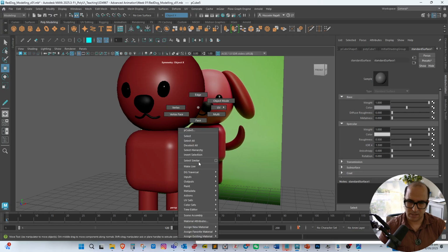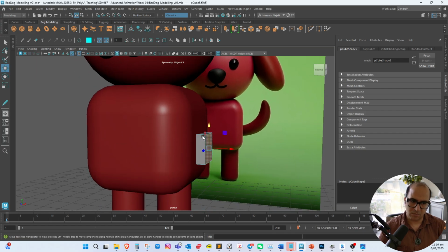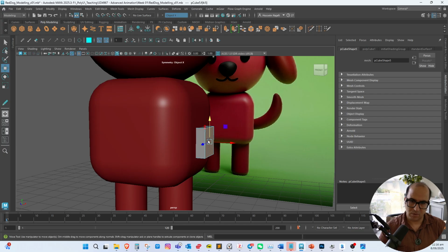Extrusion is that if you want to extend, so what I do is I select one face and extend it along the path. I think it's this tool, extrude, or my favorite way of doing it, shift right click, extrude face.